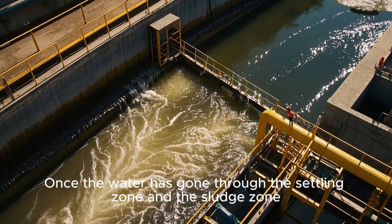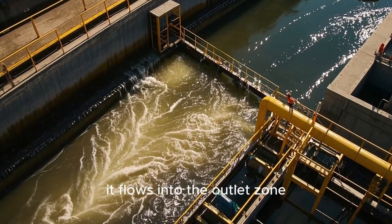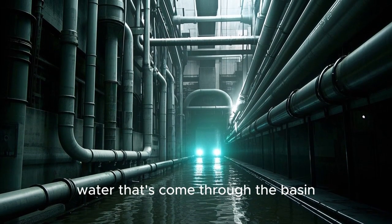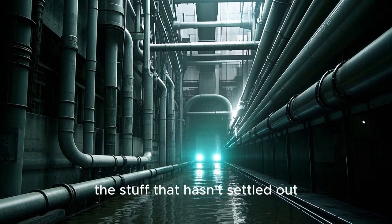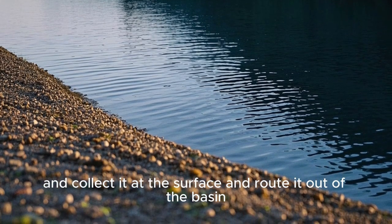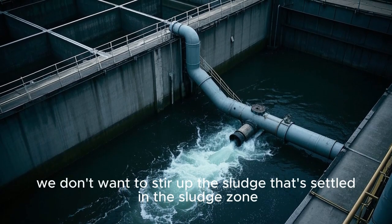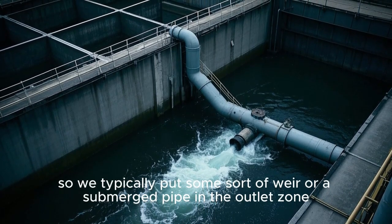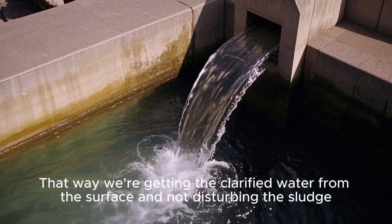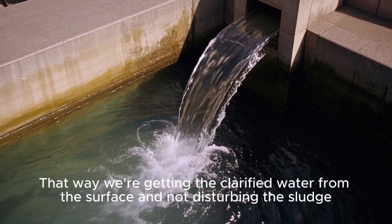Once the water has gone through the settling zone and the sludge zone, it flows into the outlet zone. The goal of the outlet zone is to collect the clarified water that's come through the basin, the stuff that hasn't settled out, and collect it at the surface and route it out of the basin. Again, we don't want to stir up the sludge that's settled in the sludge zone, so we typically put some sort of weir or submerged pipe in the outlet zone. That way, we're getting the clarified water from the surface and not disturbing the sludge.